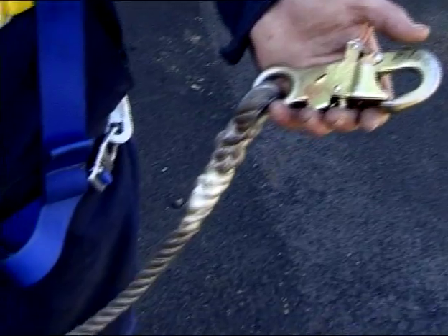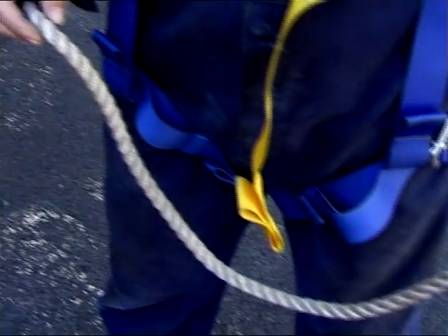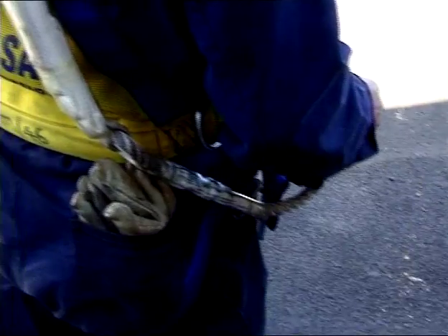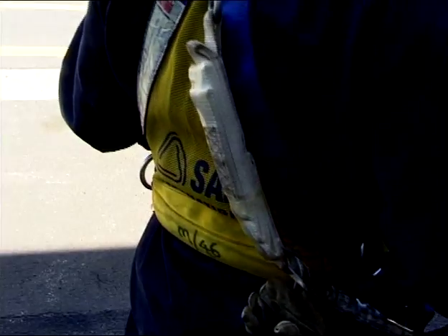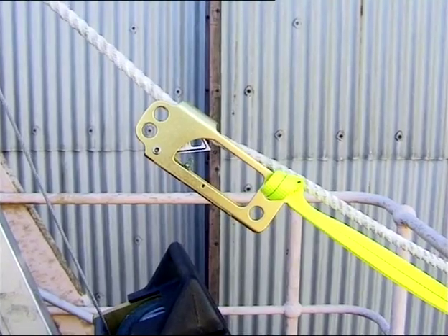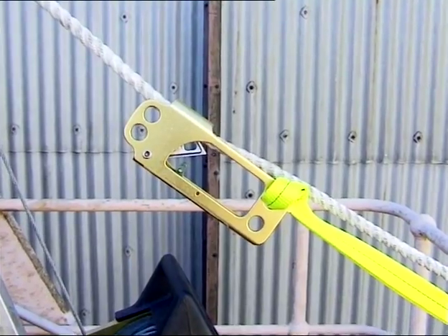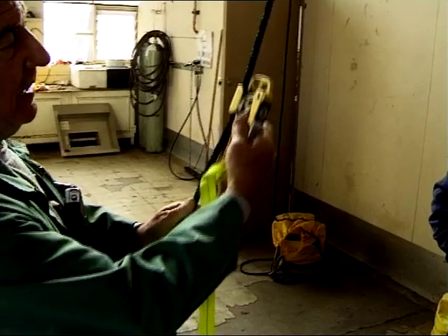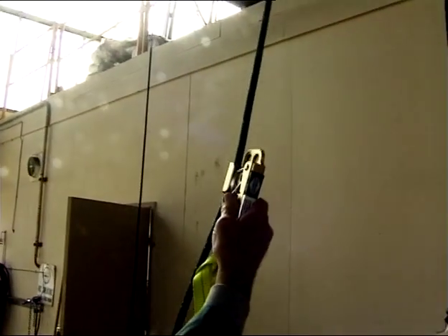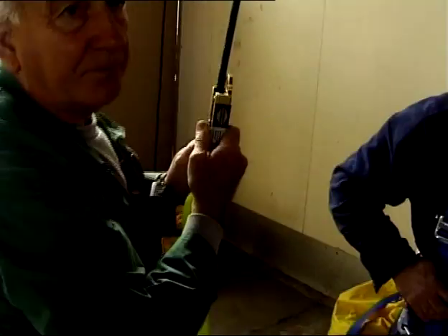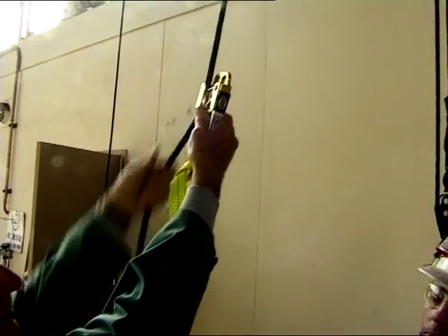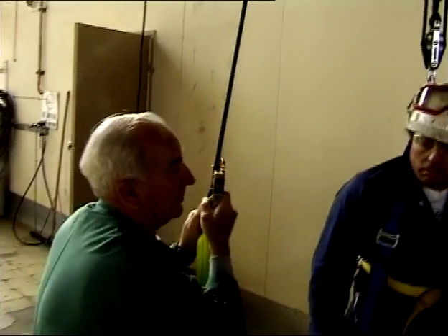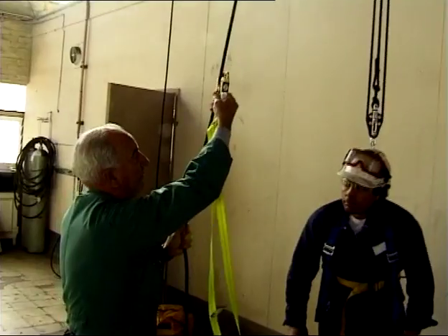The lanyard is a flexible line of webbing, synthetic rope or wire rope that runs from the fall arrestor or lifeline to the body harness. The fall arrestor is a device that automatically locks onto a lifeline when a fall occurs. Normally, it will travel freely along the lifeline, but when sufficient sudden force is applied, it will grab onto the lifeline in the same manner that a car seatbelt will grab in an accident.